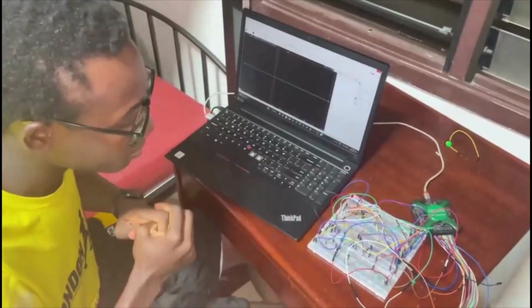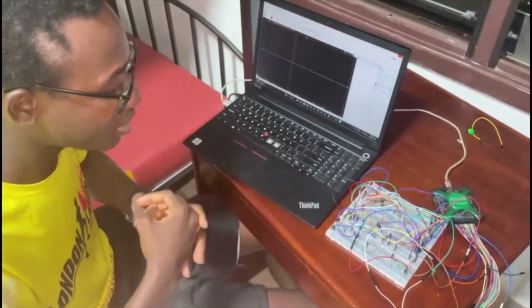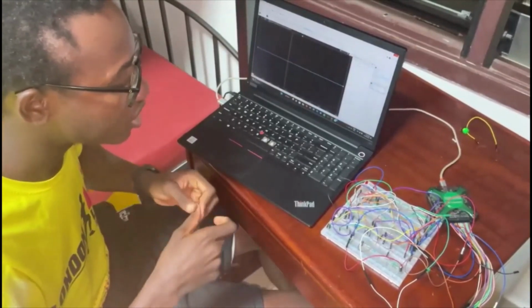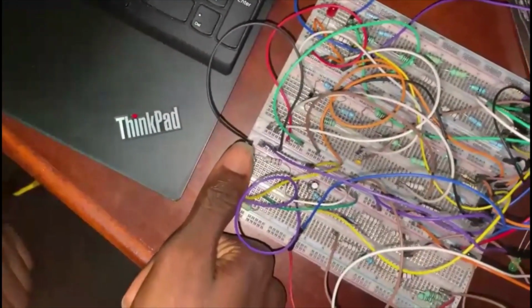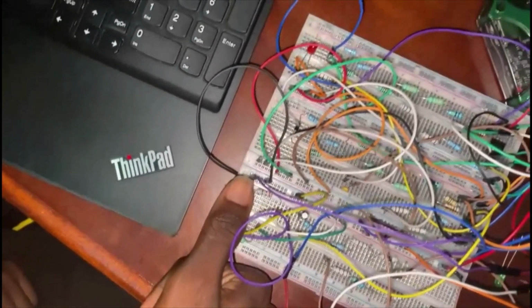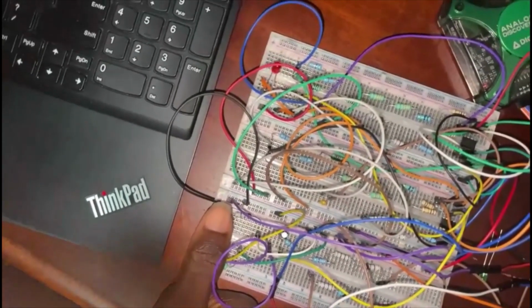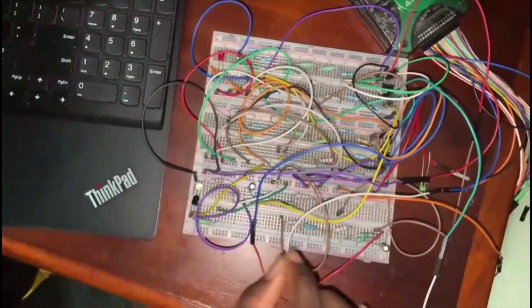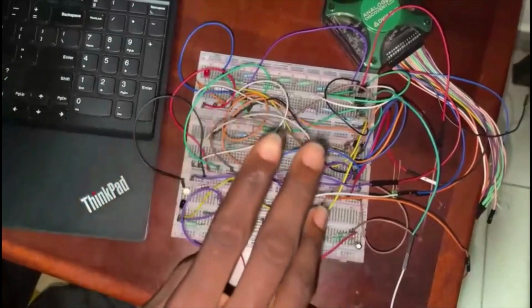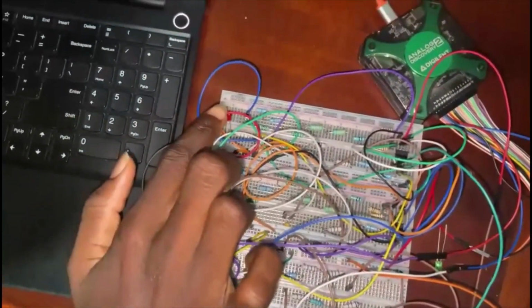So basically, the project uses the transmission and then receiving of an IR signal, which would be transmitted through your thumb when you place it on our sensor. Depending on the state of the vein, whether it is closed or open due to the flowing of the blood, we can receive that signal and then filter it through some active and passive filtering systems. Then you can amplify it to blink this LED you are seeing here.